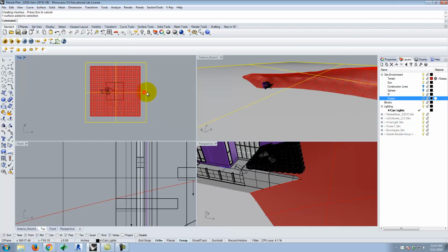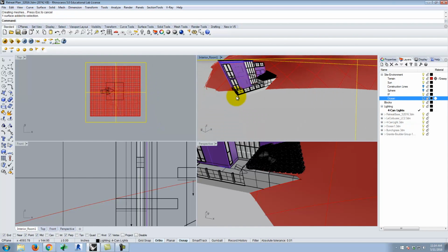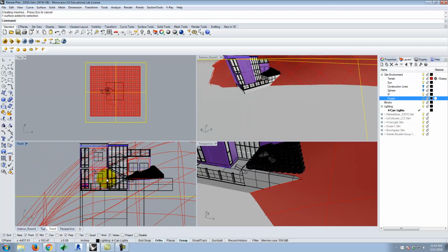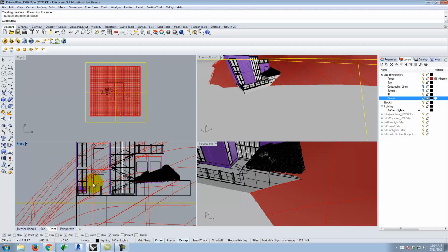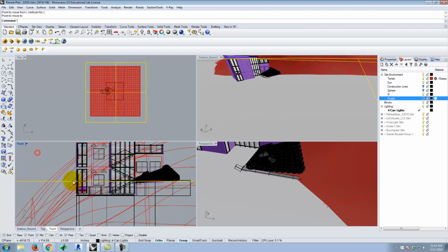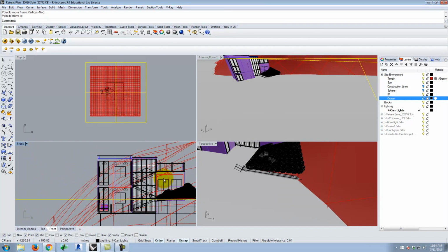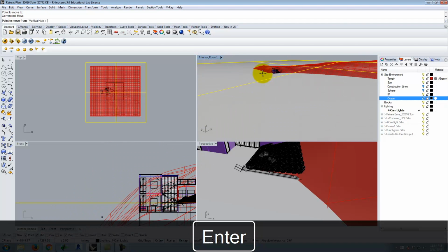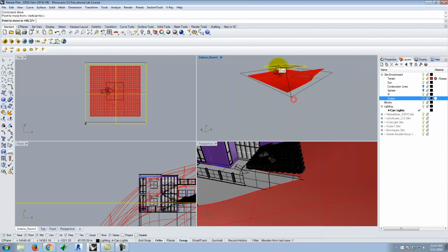There it is. And I'm going to adjust this so that it is at a particular level that would be 4 feet above whatever floor that I want to cut through. And I'm going to choose to cut through my second story because it will cut through this back room and this room at once. If I were cutting through at 4 feet above the first story, I wouldn't get anything of that back room. So because I'm only doing one plan, I think that one's going to be the better option. So let me go ahead and I'll move from one corner back over here.